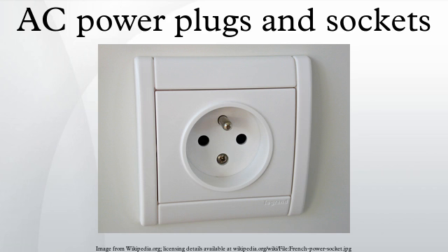Since the early 1990s, earthed sockets have been required in all new electric installations in Denmark. Older sockets need not be earthed, but all sockets, including old installations, must be protected by earth fault interrupters by July 1, 2008. As of July 1, 2008, wall sockets for French 2-pin, female earth CEE 7/5 are permitted for installations in Denmark. This was done because no electrical equipment sold to private users is equipped with a Danish plug. Sockets for the Schuko were not permitted until November 15, 2011.